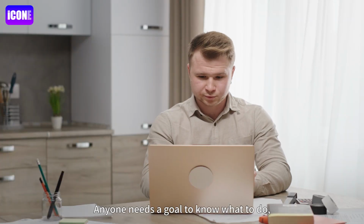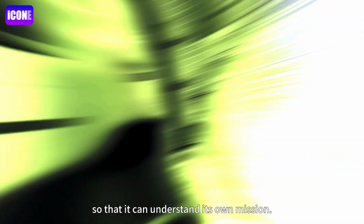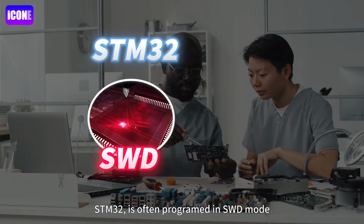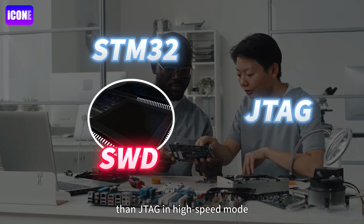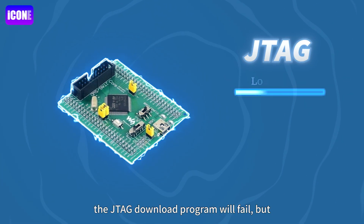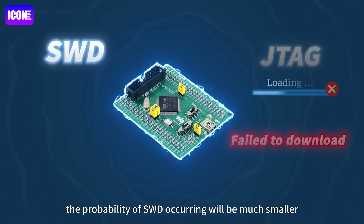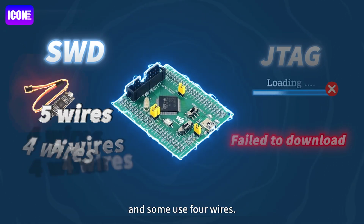Anyone needs a goal to know what to do, and the microcontroller also needs to be injected with a program so that it can understand its own mission. STM32 is often programmed in SWD mode because it is more reliable than JTAG in high-speed mode. In the case of large data volume, the JTAG download program will fail, but the probability of SWD failing will be much smaller. Generally, only 5 wires are needed, and some use 4 wires.